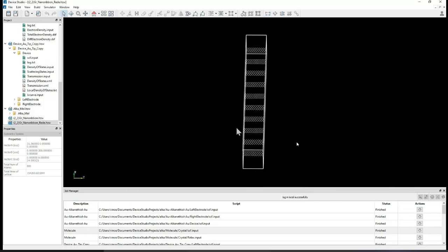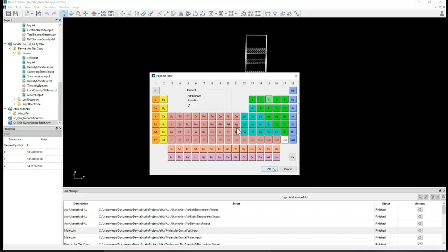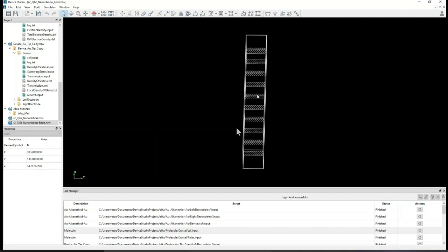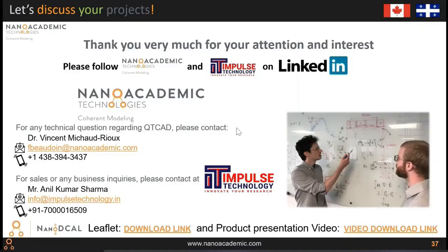And then you can use a selection tool, select an atom, and then just replace it by, let's say, a nitrogen atom. You could do the calculation and then study the charge around there and the charge density difference. Also relax the structure. And for sure, this kind of material analysis is part of the tool. Okay, sir. Thank you, sir. You're welcome. Thank you too for your question.